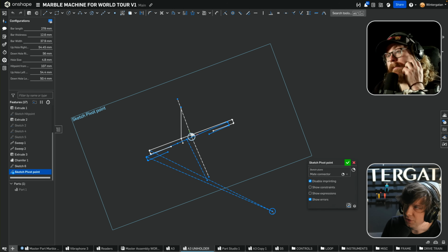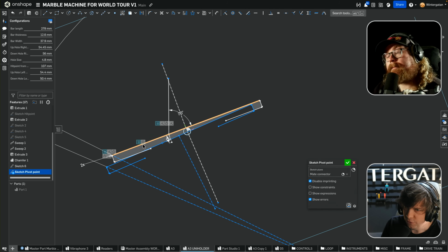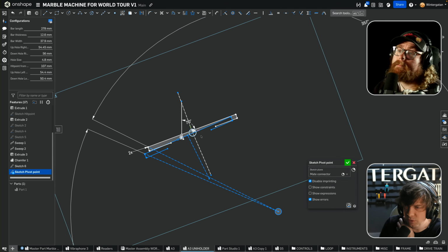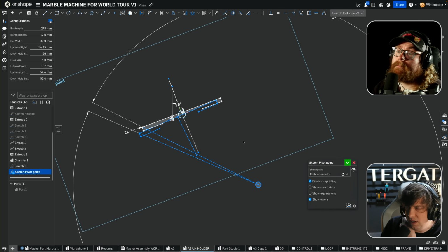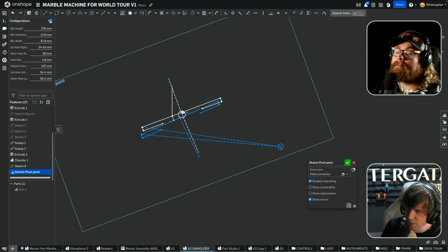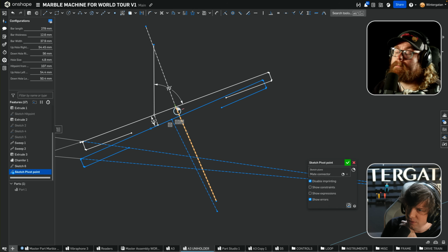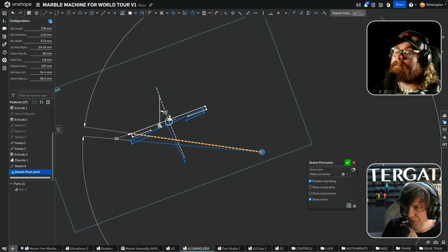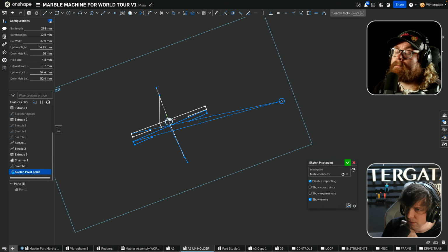So when I move the pivot point down, we will have a much more forward movement of the plate, which will be harder to cut a good slot. So we want this blue line and this white line, if they can follow each other as much as possible, the slot will be smaller and easier to make. So that's why a high pivot point like this